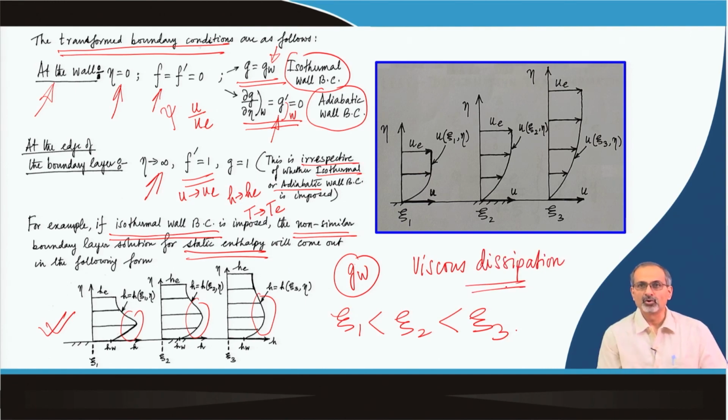As the flow slows from a very large free stream value to the no slip condition at the wall, very large viscous dissipation occurs, and that increases the internal energy of the gas, and that reflects in enthalpy as well due to the temperature rise. And you see that H has a typical profile which peaks somewhere inside the boundary layer.